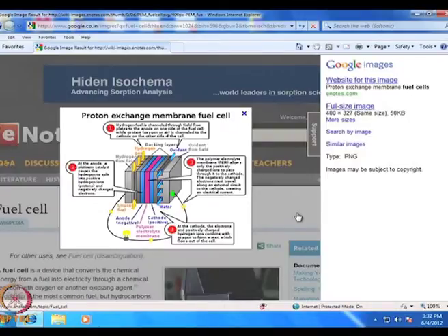Would you be very surprised if I said that this whole fuel cell assembly can be sealed by immersing it in tetraethyl orthosilicate alkoxide media, so that the TEOS covers all the surface, fixes all the leaks, and that fuel cell now becomes leak proof?